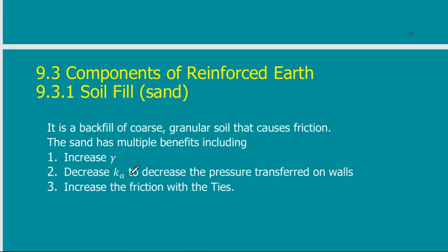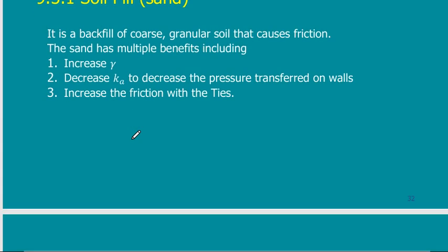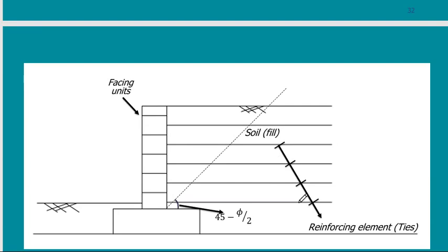Of course, if I want better sand, I would bring sand with a high value of phi, so that I would have big strength for this sand. Usually, if I have a wall like this and I have the soil backfill here, and this is the full system, if I don't have a wall, what will happen? This line will fall.